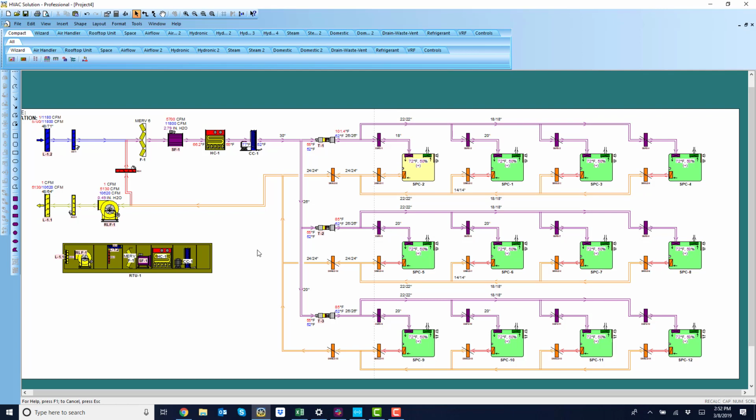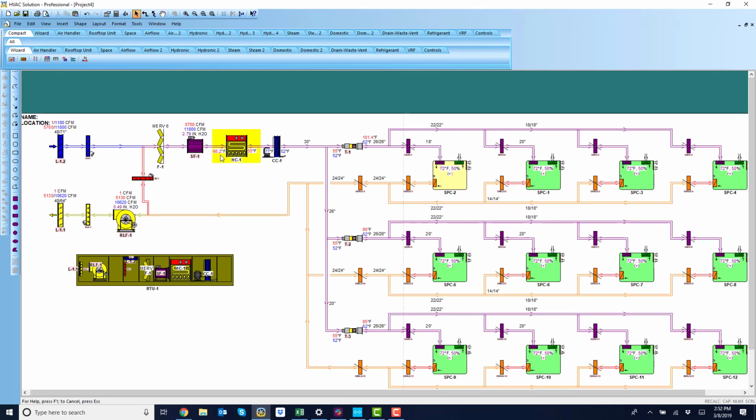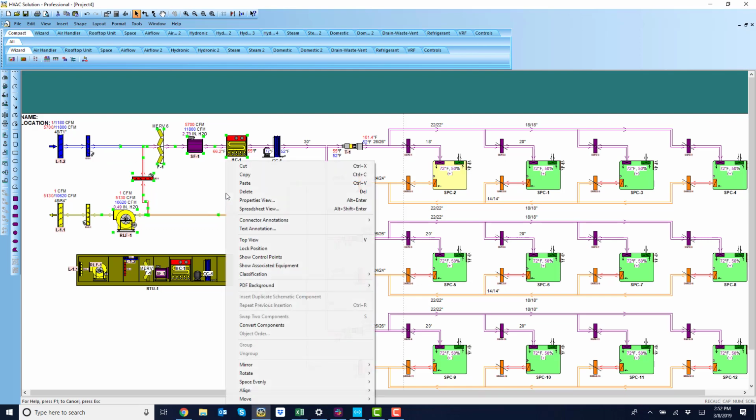Remember, we have about 60 manufacturers where we've integrated their selection. So we create equipment schedules from this equipment where the schedules and the schematics will now go on your drawing. You'll notice here, just a little engineering thing, I don't need this heat exchanger in my rooftop unit because it says 66.2 degrees air. Well, let's look at the temperatures here in that duct.